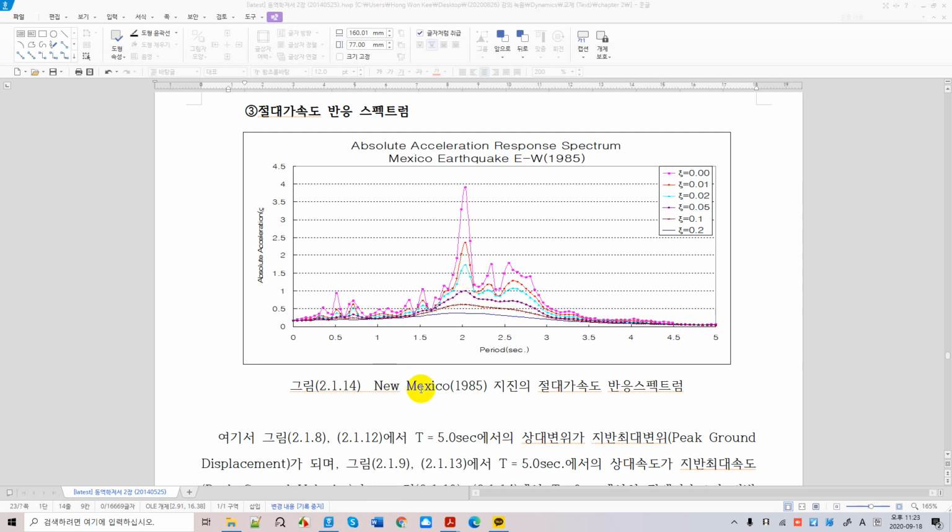Looking at the Mexico City earthquake, this represents a maximum response, and we chose acceleration for this case. The y-axis is accelerations, and we say spectral acceleration, denoted SA. Spectral means maximum value for seismic design. So this is maximum acceleration, or maximum velocity, or maximum displacement.